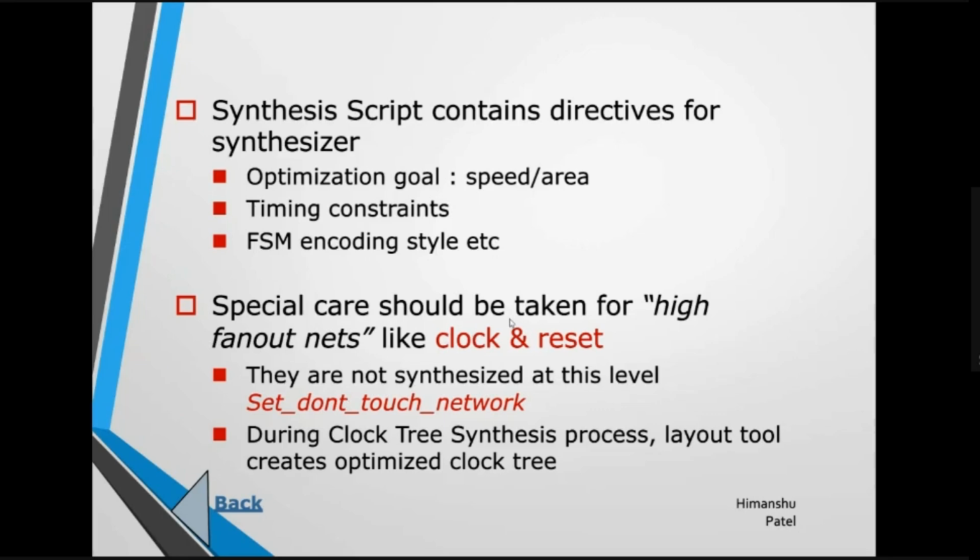Special care should be taken for high fanout nets like clock and reset. Yes, because clock and reset are the major control signals of all the flops in the design, which plays a key role. The entire SoC can go into the trash bin if one particular clock or reset is not functioning as per the requirement during testing.